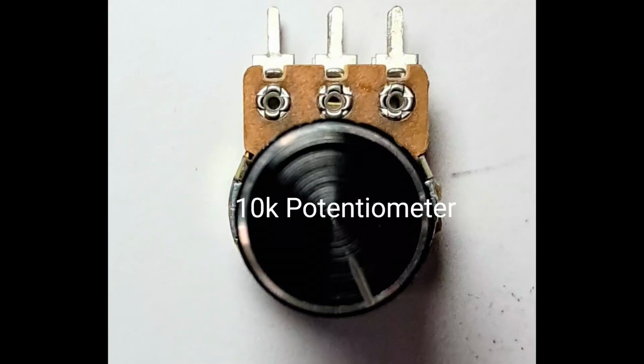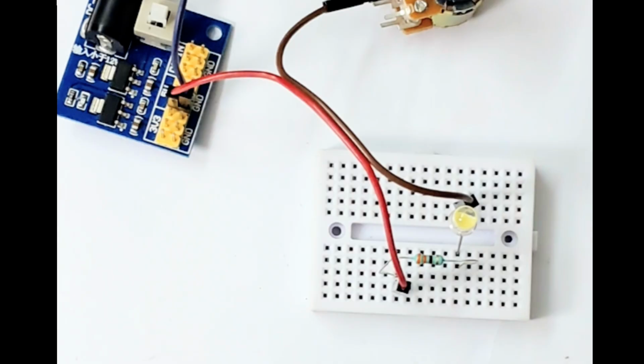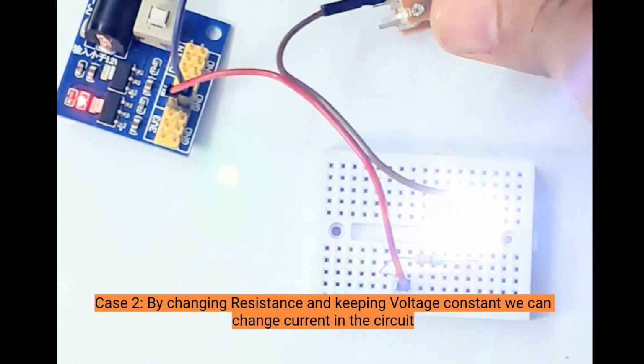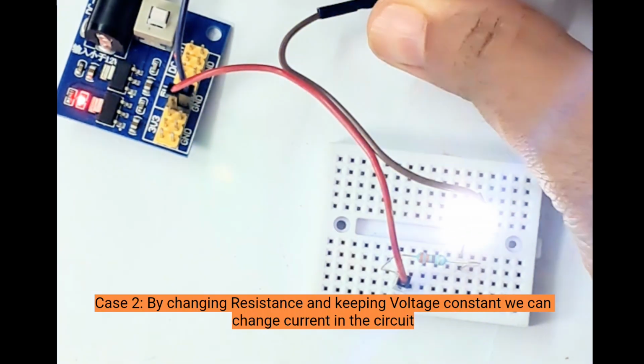Before we move to case 2, let's understand the potentiometer. The picture in the image is a 10K potentiometer or a variable resistance. It is used to vary the resistance in a circuit. You can find 10K at the end terminals and the middle terminal is a variable. As you can see, keeping the voltage the same and increasing the resistance will decrease the current and vice versa.